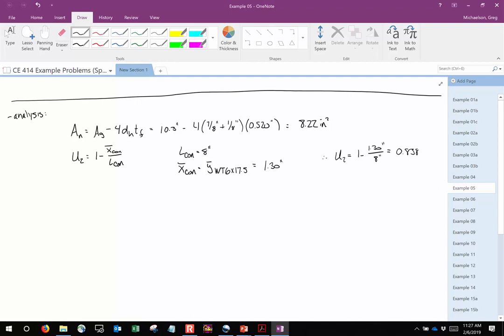Everybody okay with that? What about case 7? Does case 7 actually apply? And why is that? It says 3 or more fasteners per line. Do we have 3 or more fasteners per line? How many do we have per line? 3. We have 3 fasteners per line. So we have case 7 that we need to assess.